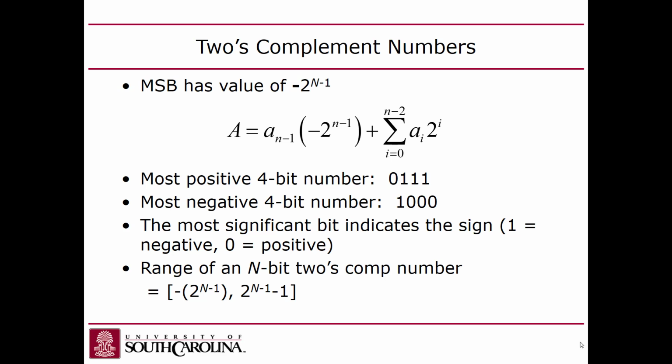So 0, right? 1, 1 with another carry, right? 1, right? And that would be a 0 with a carry. So that would give me what appears to be 6, right? But that actually also had a carry. So in that case, the way I would detect that would be I would have to look at the sign bits of the two numbers I'm adding, as well as the sign bit of the result I get, and that would indicate something's wrong.